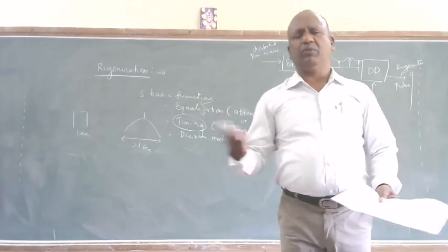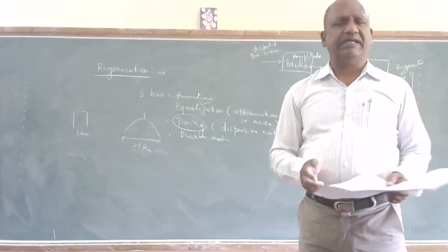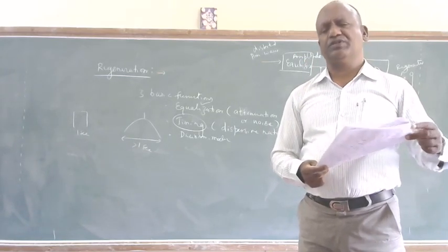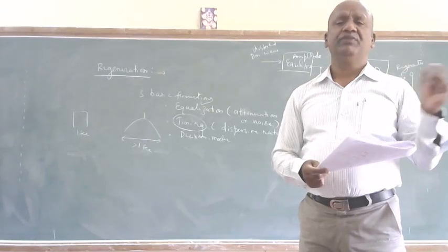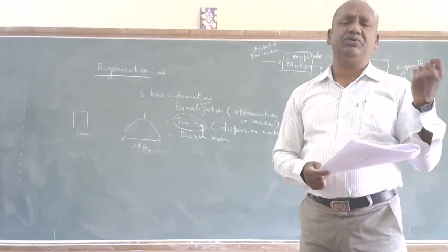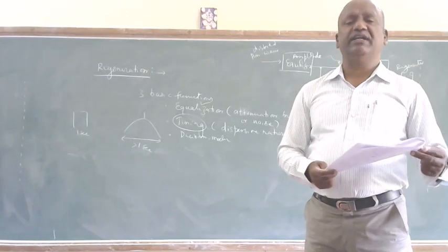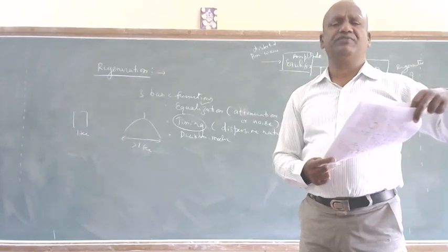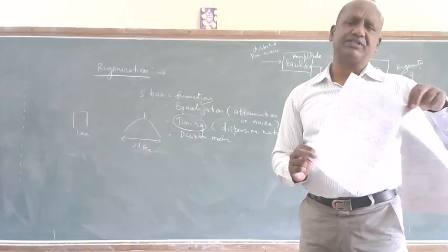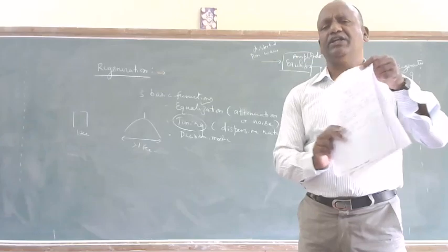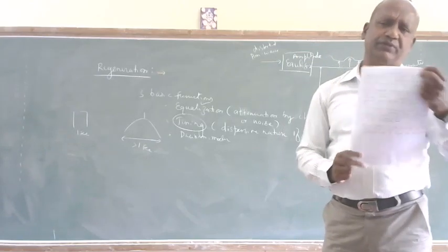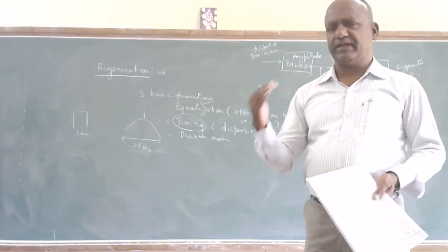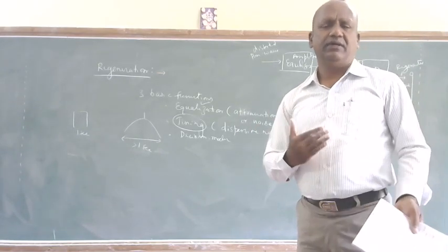After decoding, it is given to a low pass filter, basically called a low pass reconstruction filter. With that reconstruction filter, it is possible to get back the original signal by taking the input sample values and using the sinc function as an interpolation function. With the sinc function as the interpolation function, the low pass filter with input sample values can get back the original continuous analog message signal at the output of the PCM receiver. With this, the PCM system, along with the transmitter block diagram, channel and receiver, is complete.